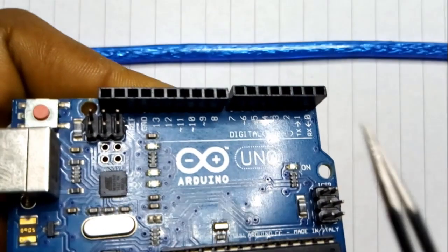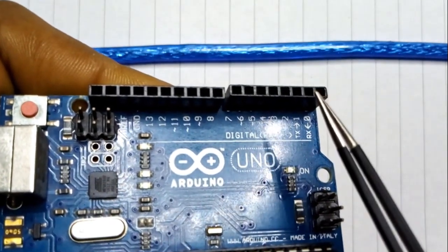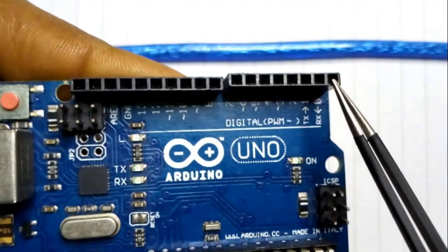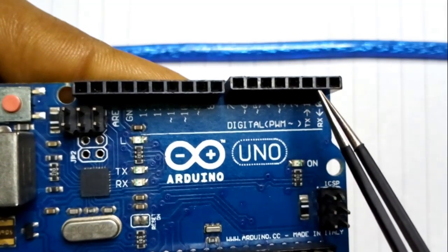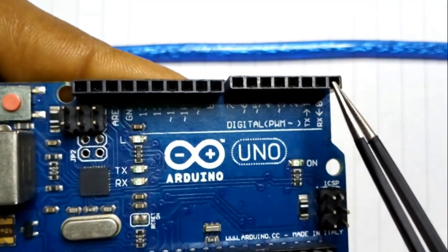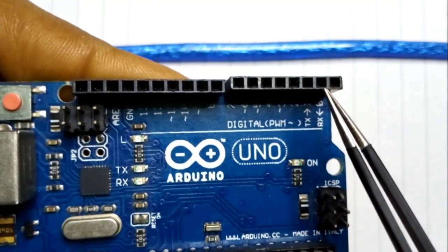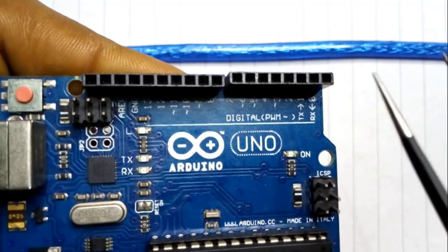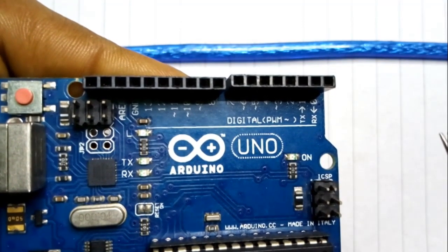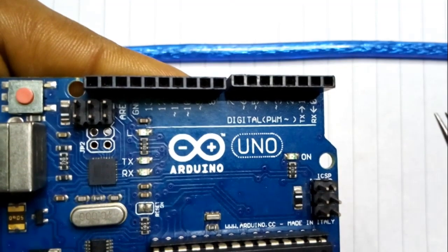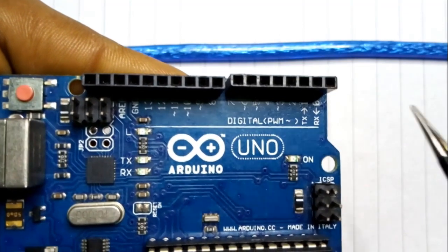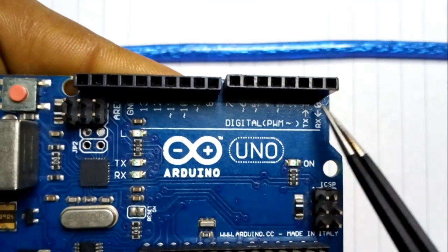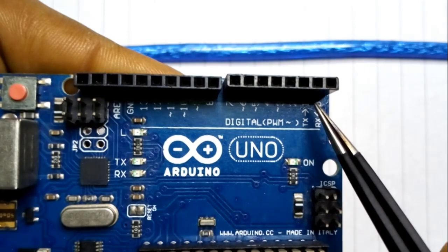Okay, so this is digital pin 0. You can see the label here. This is digital pin 0 and this is digital pin 1. Now these two pins are used for what we call serial or UART communication. UART stands for Universal Asynchronous Receiver Transmitter Communication. Digital pin 0 serves as the receiver, or the RX pin, and digital pin 1 serves as the transmitter